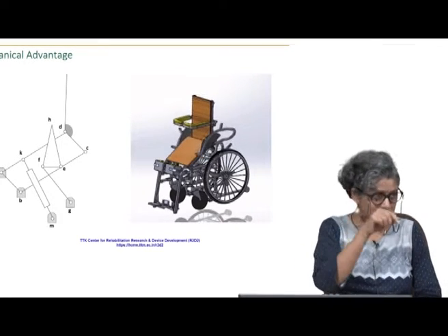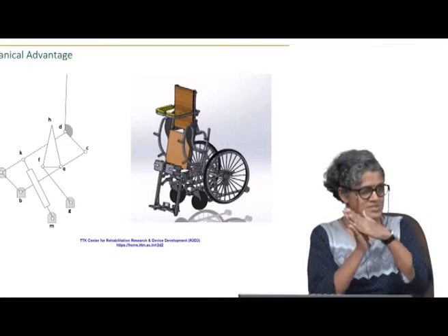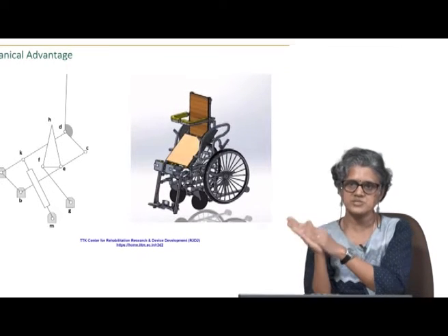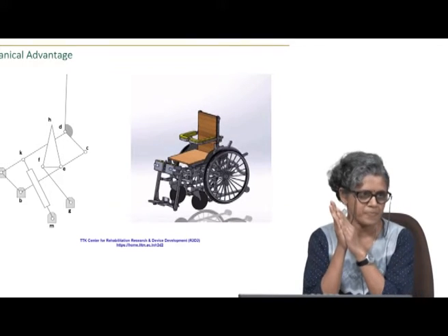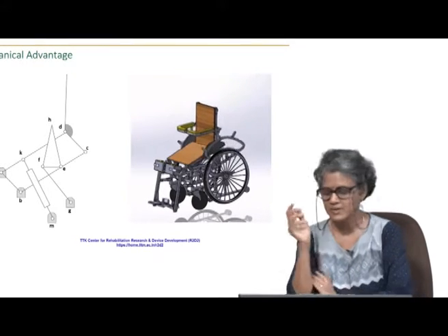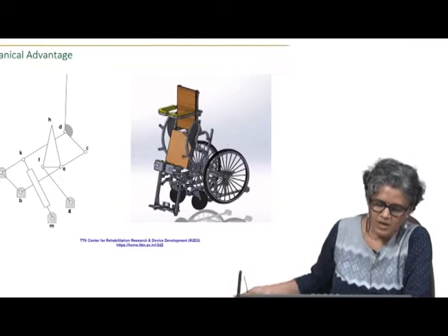So, the linkage dimensions are chosen such that it toggles at the sitting position and toggles at the full standing position, so that you do not go beyond that.